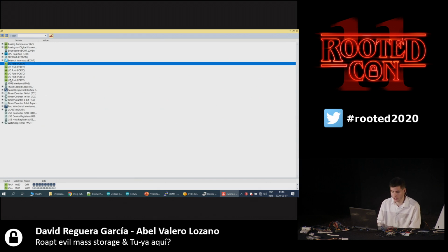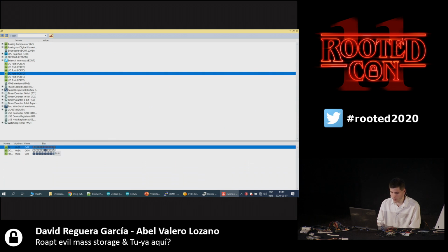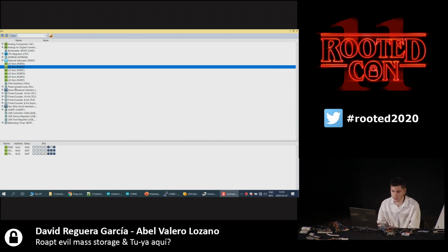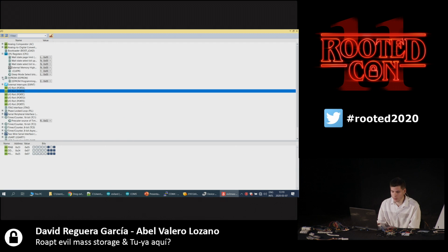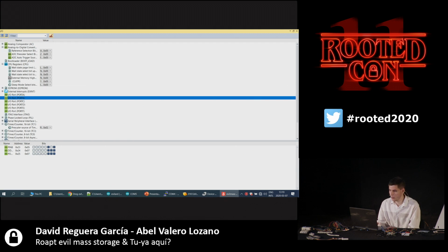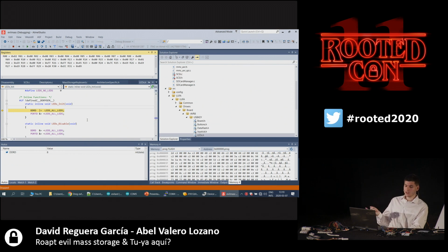Here you can see the microcontroller ports. I want you to see them, so I double click here and I change the pins and see what's going on. So we are interacting with what happens here. We have the timers, we have the USARTs, we have the registers, we can see how EEPROM is doing. We have many things here, and this would be the development. It's not very different from developing a C program, and this way it will be debugged.